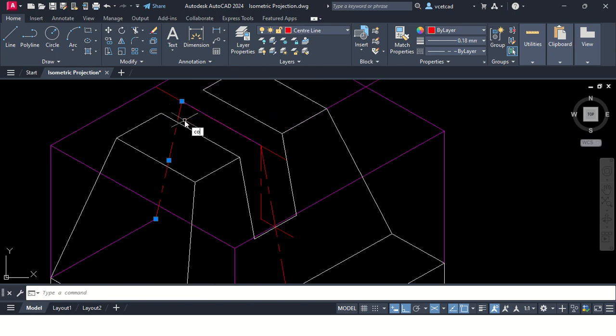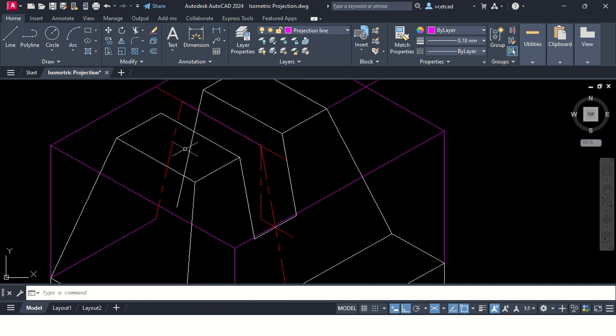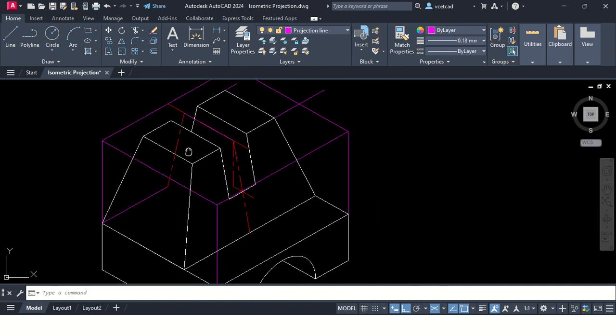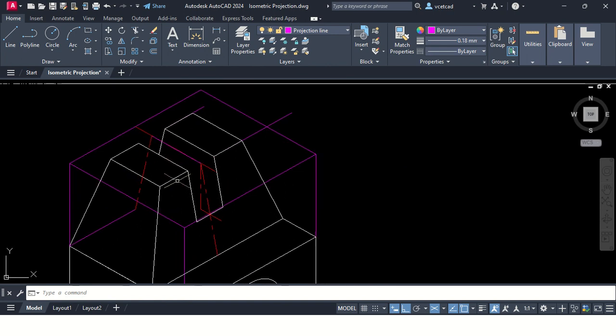I will copy this line now. See how to transfer that point. Copy it, transfer it to this point. Okay, and now what I will do, I will select that line. I will convert it into outline. Okay, TR double enter. This portion is not required. This portion is not required, so trim it off. So can you observe this line is not vertical. This line is inclined, and for that we have taken that reference.